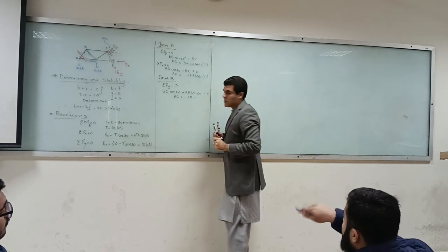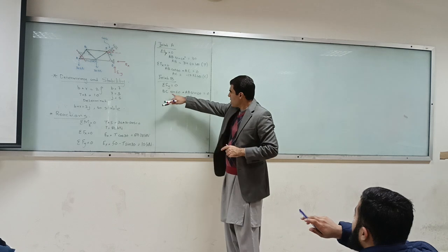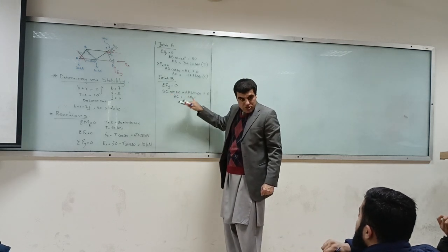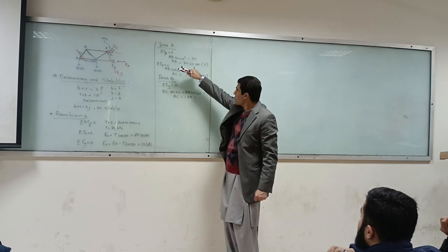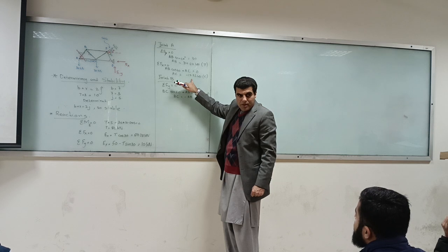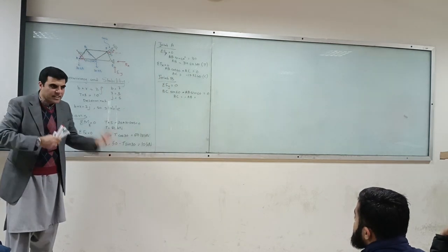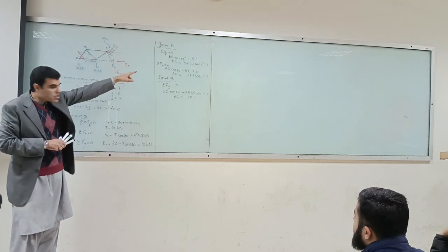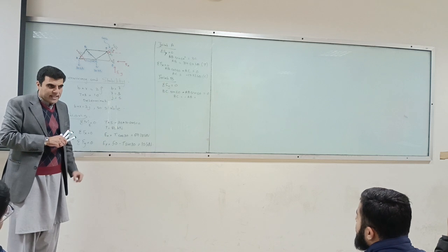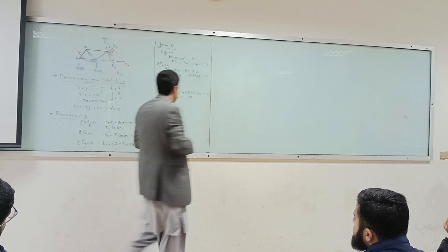One is in tension and it is downward, and the other is in tension and it is upward. But that's what I'm saying, that once you put this in the equation, when you're solving it, then you put the actual value which you would have already found. So you assume first of all that they are directed away, assume that everything is in tension, and then use the one which you have already calculated. Use that, and you will get your signs automatically. They will be adjusted.